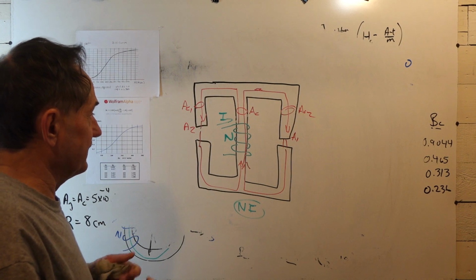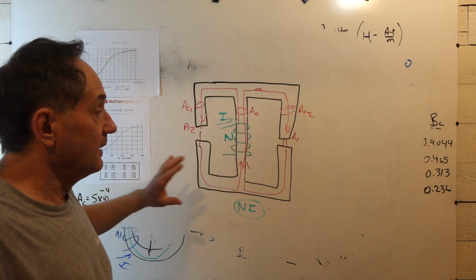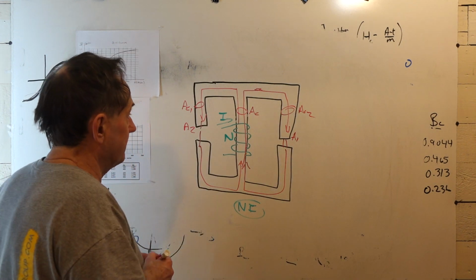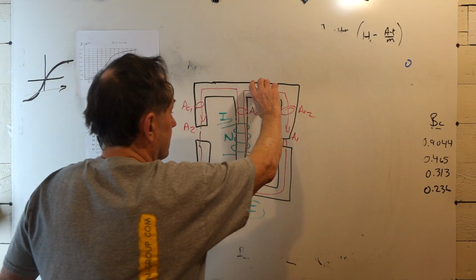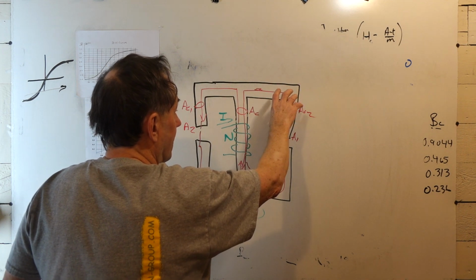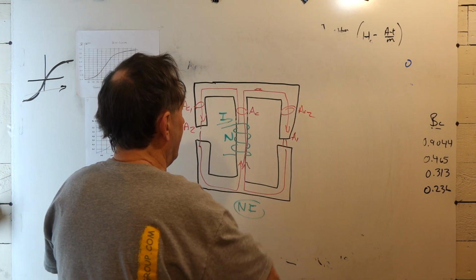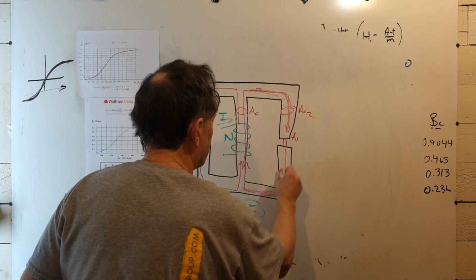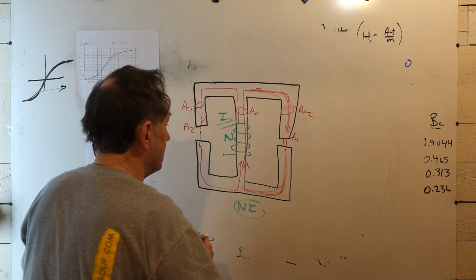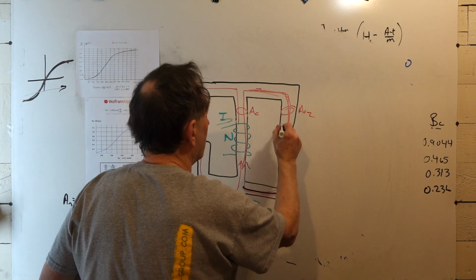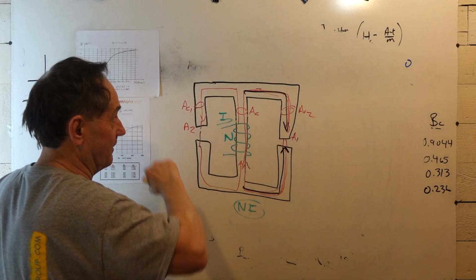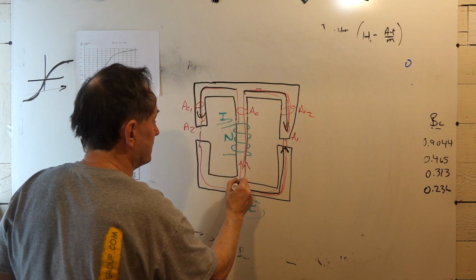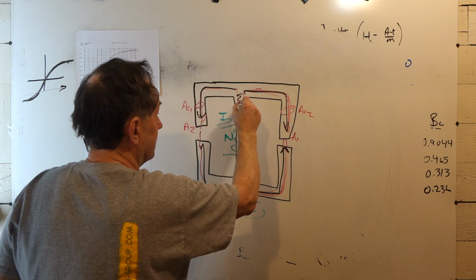But even if it's this much more complicated, you build yourself a table, and what you do is you take guesses of how many ampere-turns are allocated to this and this portion of the core. Say this portion of the core, that and that would be the same. And then an allocation for this portion of the core, and then in the center.